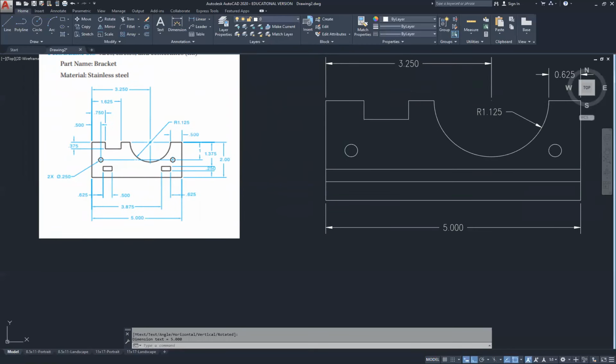As a matter of fact, this is a dimension that's called a redundant dimension. It's over-dimensioned. So typically you don't see dimensions following up one step after the other. It typically leads to the dimension being over-defined.